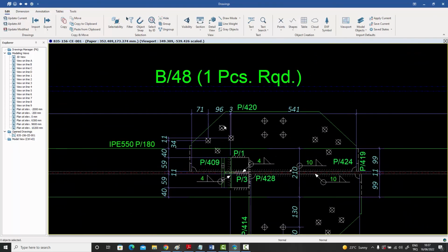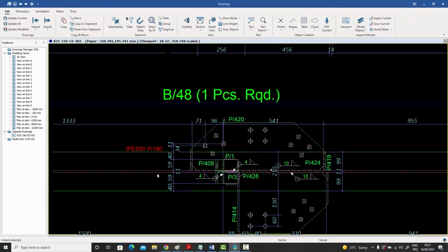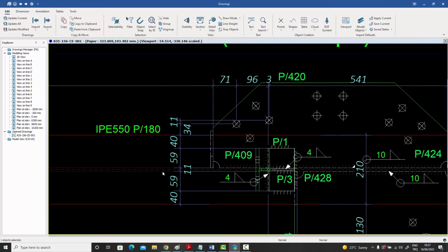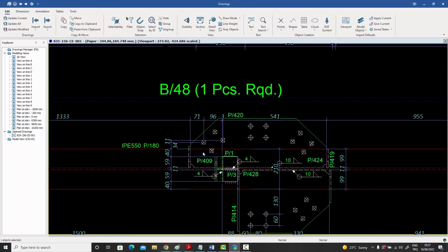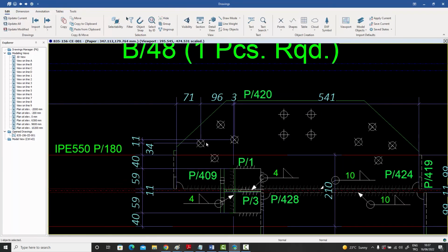and then we had talked about a setting for how the parts on the assembly will be dimensioned. So if you notice over here, it has dimensioned according to both the edge of the part, as well as the bolt over here. So we can modify whether we want this. We talked about certain tolerances, that this plate might be cut at a bad tolerance, or this rolled profile might have a web thickness which is slightly smaller, or the length might be cut a bit. So if you dimension your part by bolts, it's usually a better practice.